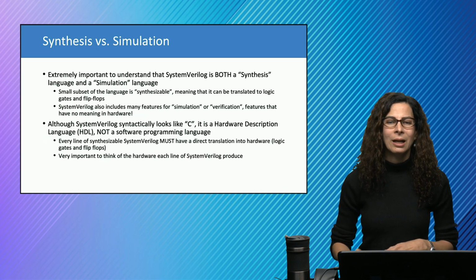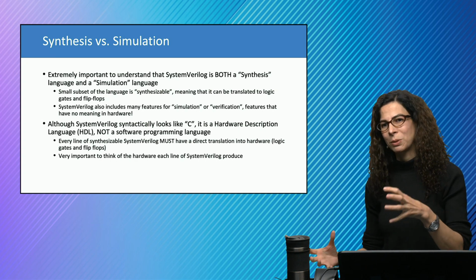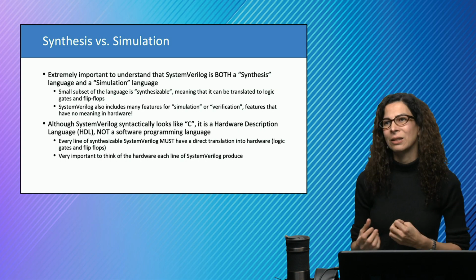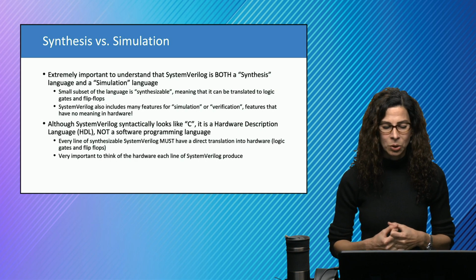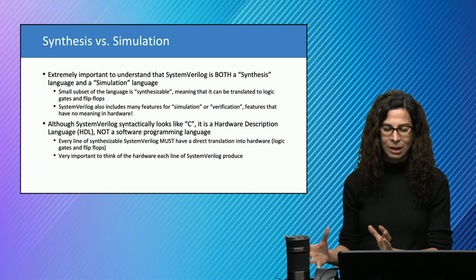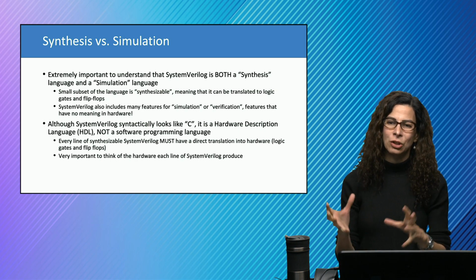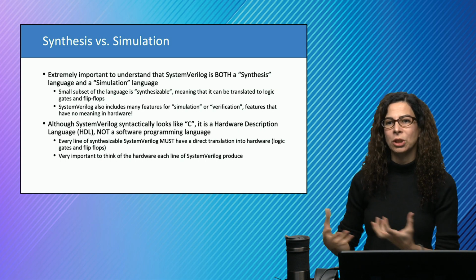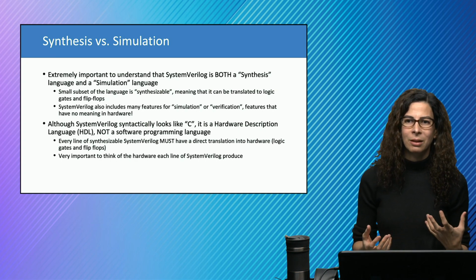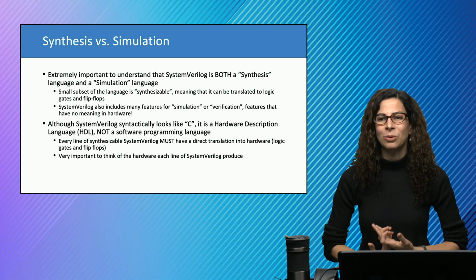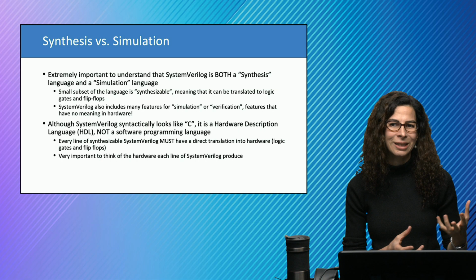The other thing to know about hardware description languages is that because it is compiling things to a piece of hardware, there are two usages, as we've seen earlier, synthesis and simulation. You need to understand that there are things that we can do in simulation that are not synthesizable into hardware. For example, you could have constructs for testing or verifying each of your blocks that you don't synthesize once you use this to program a piece of hardware. You may, for example, use something like a printf, which prints the output for you, but you don't have that in a synthesis environment. This is only for simulation because you want to see the inputs and the outputs.